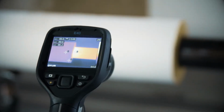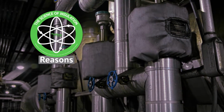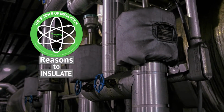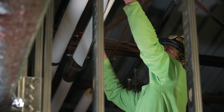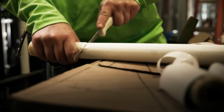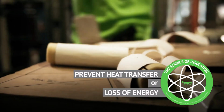Using an infrared camera is a great way to see materials that have good radiation properties, materials that have poor radiation properties, and where there is a difference. Now that we know what the three types of heat transfer are, let's talk about 5 main reasons to insulate. All of these reasons center on the fact that mechanical insulation is affected by the ambient temperature that is directly surrounding the mechanical system. The first reason to insulate is to prevent heat transfer or loss of energy.